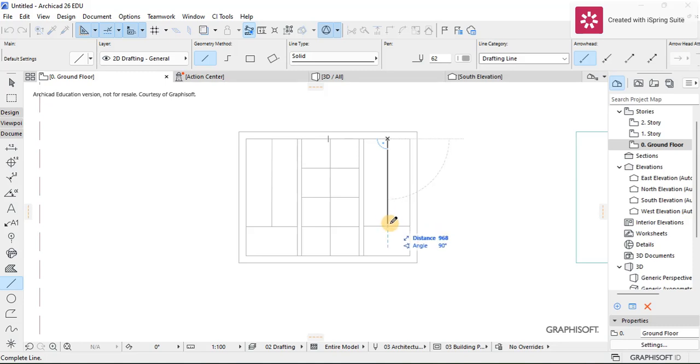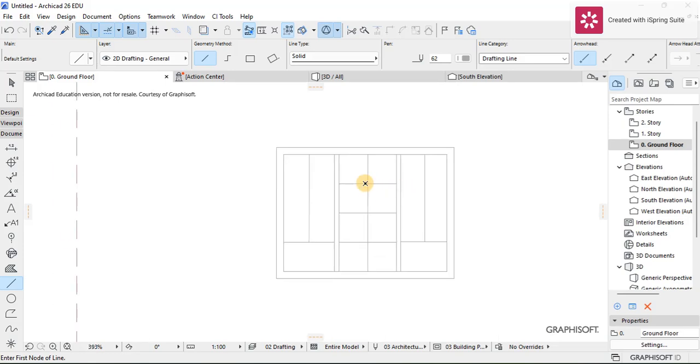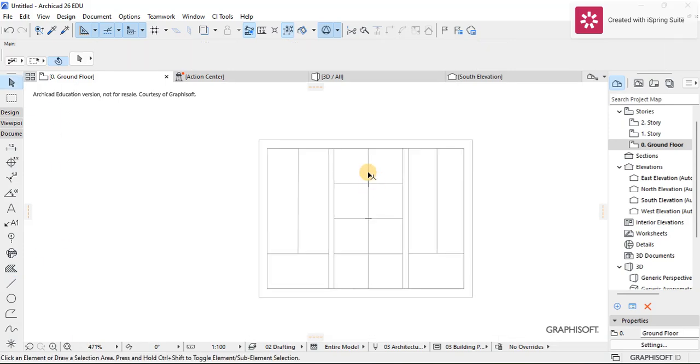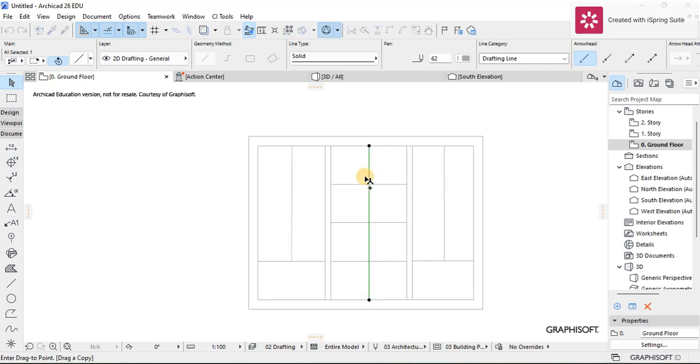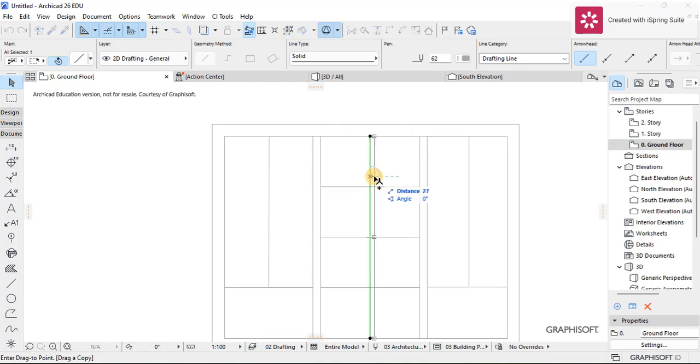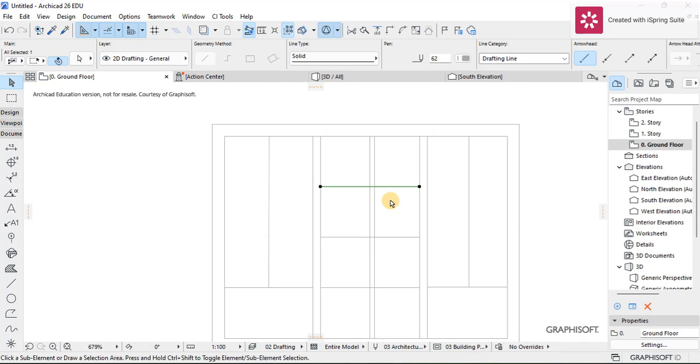So the next thing I'm going to do is make the thicknesses for these lines, because metal cannot be this thin. So I'm just going to have to drag a copy of this. Control Shift D, dragging a copy again. Let me drag it somewhere here, say by 30. And I'm dragging there. Then I'm going to drag a copy of this with Control Shift D by 30.